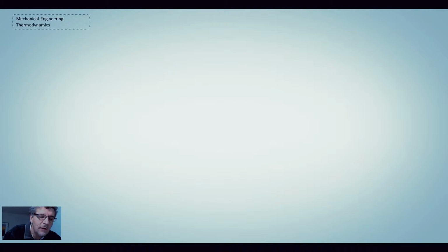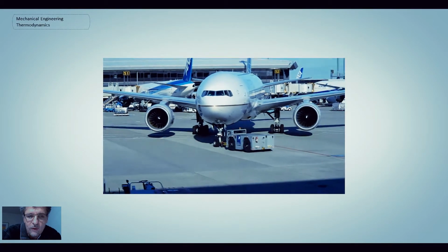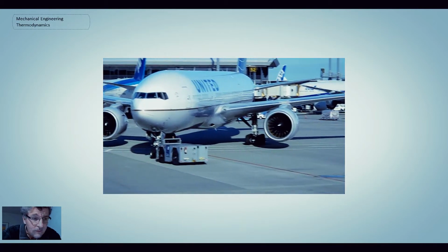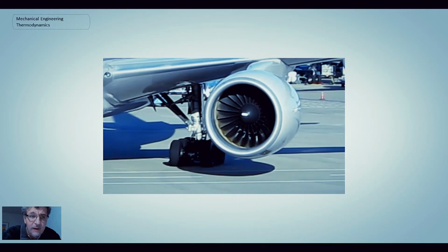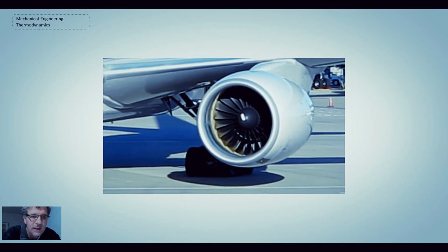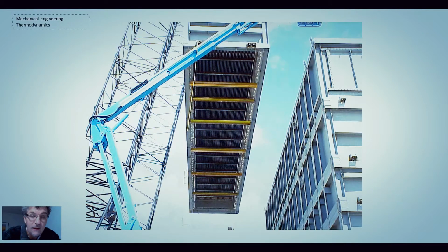So that's the essential ingredients of one of these combined power cycles. You can see it's a combination of both the Brayton, the gas turbine cycle, a different form of gas turbine, however. What we saw when we looked at the Brayton cycle, for example, on an airplane, that would be an aero application gas turbine engine. The one that's used for industrial applications, like we saw, would have other components on there. They're not as worried about weight, and so they will add other components that make it heavier but more efficient. And then the heat out of that goes into generating steam.